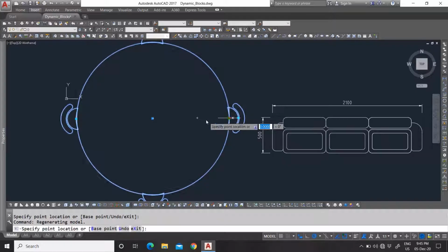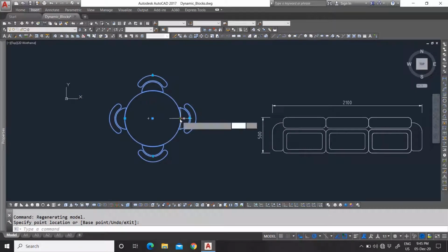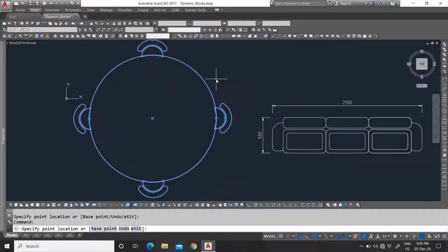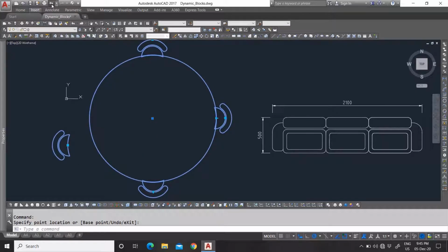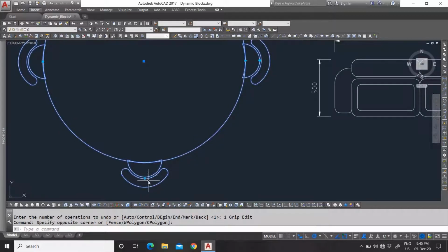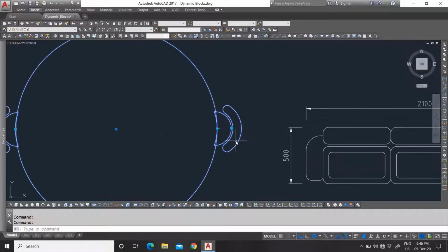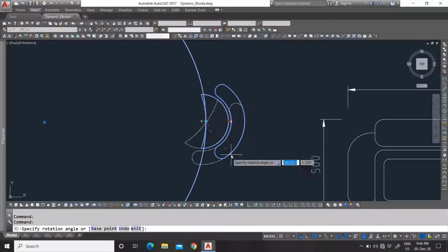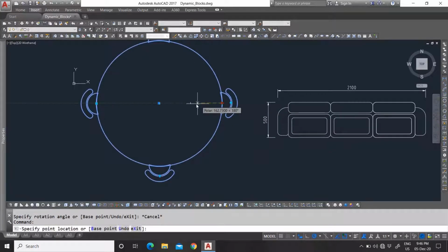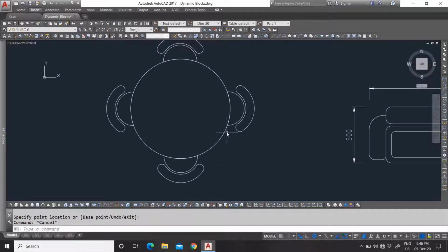You can see everything is going with whatever radius I select. Even my point is in the right direction. My flip is still where I needed it to be, and my rotation is still where I need it to be. So make sure you always select, with whatever action you are doing, the parameter you assigned it to the first time.